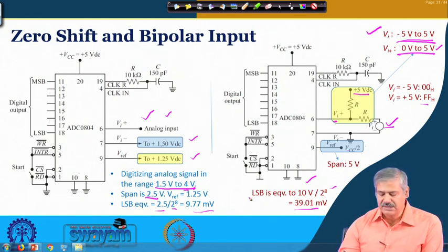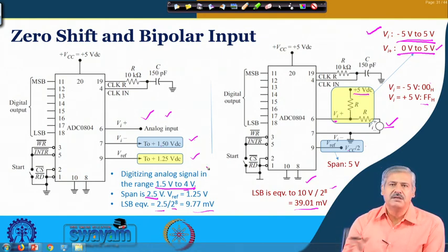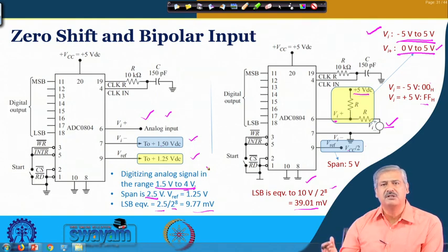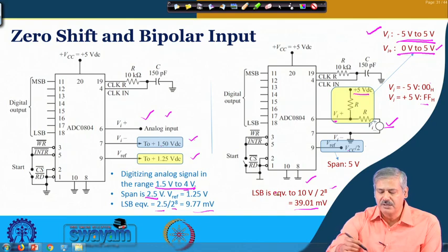These are certain important aspects. Other things associated with this ADC operation are that you can start it by pressing a switch, and there are interrupt and various other inputs when you are using it with a microprocessor or other circuits. You can make use of them, but the basic ADC operation, the functioning, the conversion of analog to digital, we have just discussed. These are other control inputs; as and when you use it, you find out from the data sheet and make use of them.